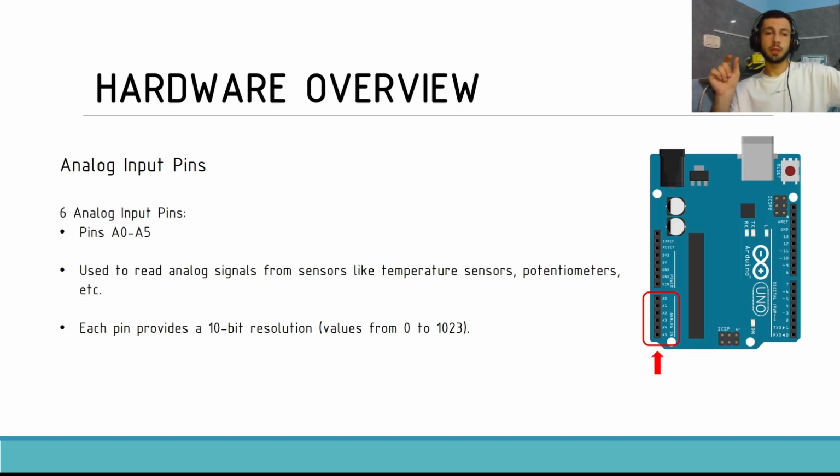The result is a digital number that represents the amplitude of the analog signal at the time of sampling. Going back to the term resolution, the resolution of an ADC determines how many discrete values it can output. It is expressed in bits. In Arduino, we have 10-bit resolution.